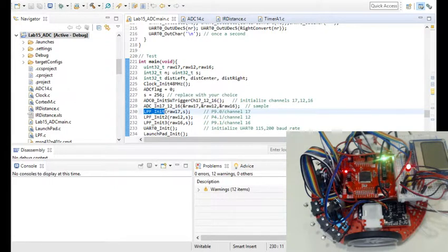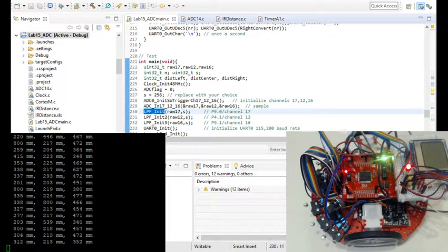But there's also a serial output as well. So you get to see the serial output from the 3 different channels, and that's coming out as well. So you have the IR sensors coming here, and you also have serial out that's going for that too. So it keeps blinking. So what I have is the center one. If I place something in front of it, I have a piece of paper placed in front of it. It sets off the blue LED, which will indicate it's the center. And then the red is for the right, and then the green is over here on the left.